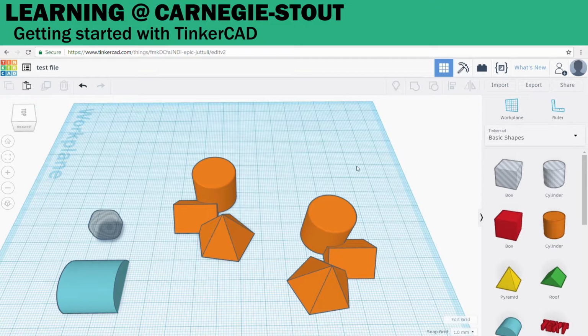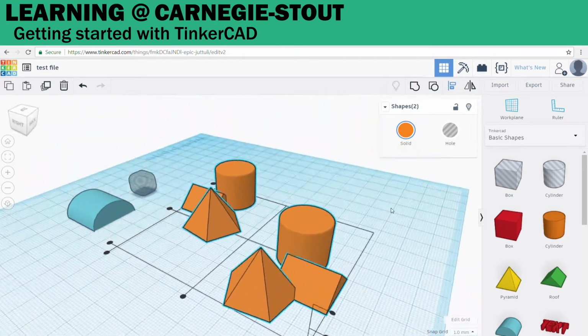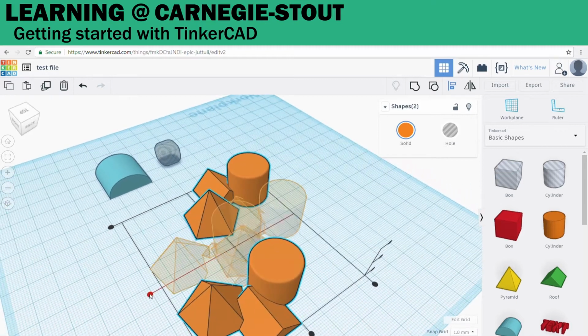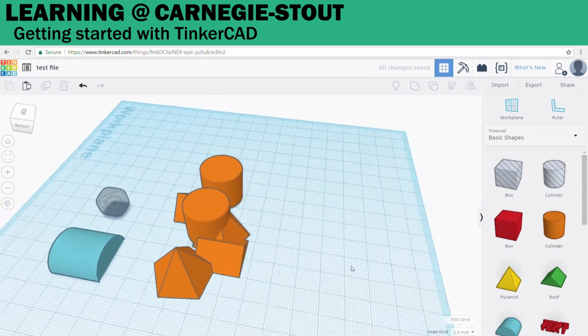Alignment is another handy tool. Let's say you want to align these two shapes. Select both of them and click on the Align button or hit the letter L. This will show you the Align dialog boxes. Mousing over any of the dots will give you a preview of what your model will look like once everything has become aligned. So if we want to make sure that they were perfectly aligned on this axis, you click the button and it lines them up.